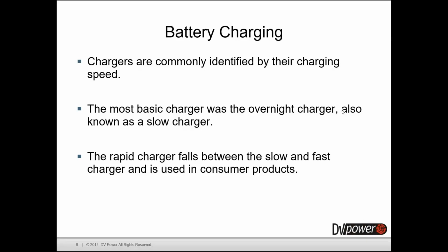Although some batteries can operate below freezing, not all chemistries can be charged when cold, and most lithiums fall into this category. So what is important here? When you buy the batteries, you will get a table, and sometimes in that table you will see that the battery can work at 0 degrees Celsius, and that is okay.